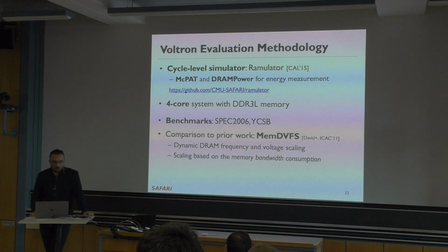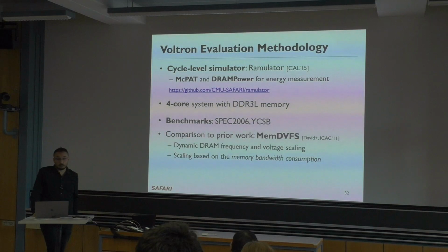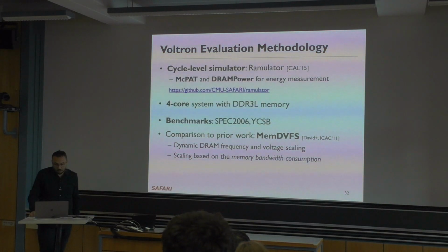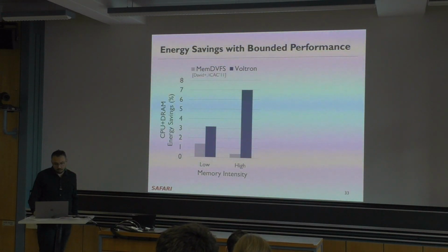We evaluate this mechanism by using McPAT and DRAMPower for the energy measurements. McPAT measures the energy of the CPU, and DRAMPower is for the DRAM. Then we use a realistic system, and we run some SPEC benchmarks and YCSB benchmarks, which are representative of common applications. We compare our work against MemDVFS, which scales the frequency and voltage together. So here are some results.